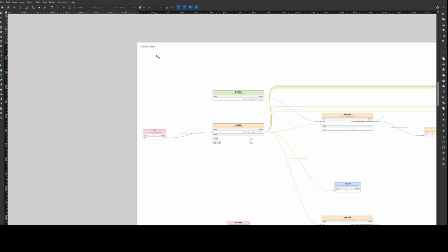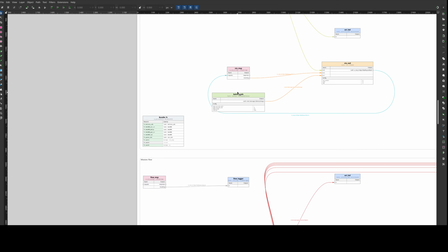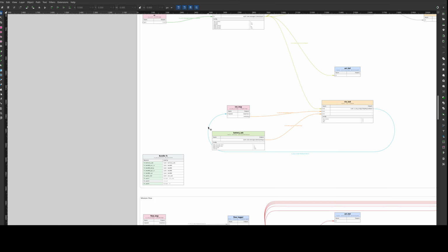But you can also have different goals, that's why we call them missions. For example, you could have a robot that is only deployed to capture data. So you could have a mission that is data collect, and the other one is basically production, where your robot is doing its normal behavior. That allows you to really reuse a bunch of things between your missions. For example, data collect usually uses the same type of sensors as the production mission. So you can reuse them from one mission to the other, and you see that there, right? There is only one part of the DAG that changes.